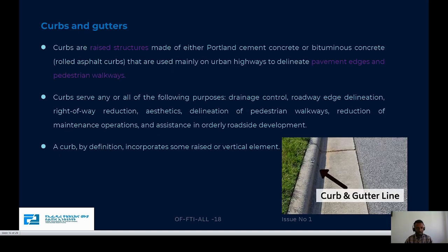And the other element is curbs and gutters. Curbs are rising structures, made either of Portland cement concrete, and sometimes bituminous concrete is used. The purpose of the curbstones is first to delineate the pavement edges with the pedestrian walkway.